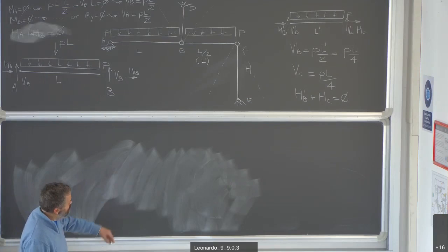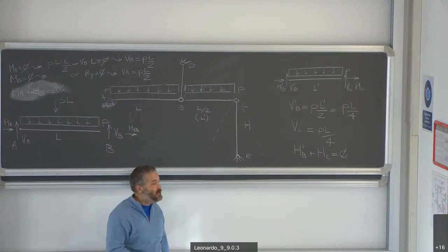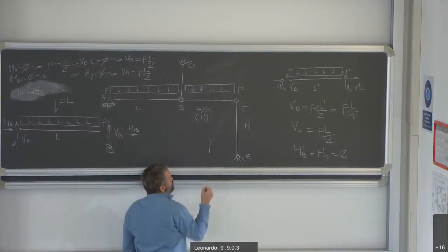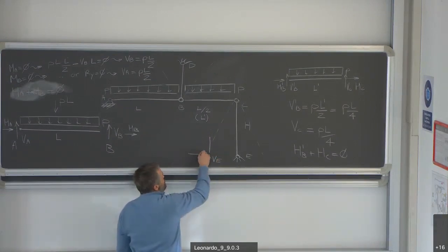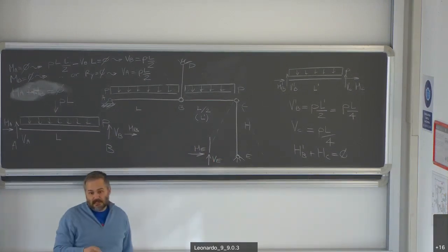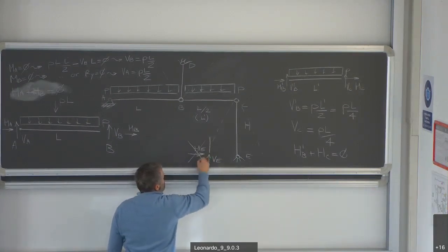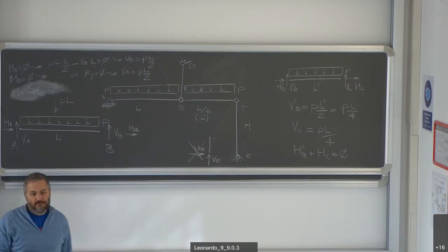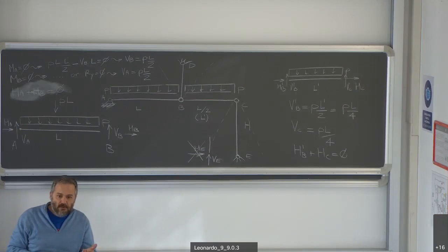Because, for example, looking at point E, knowing it's a hinge, I would have to say a priori, I expect to have a VE force and an HE force. Knowing it's a truss member, I can immediately say, okay, HE is equal to 0, only axial forces. If you don't realize this, you can always prove it by means of equations. How?